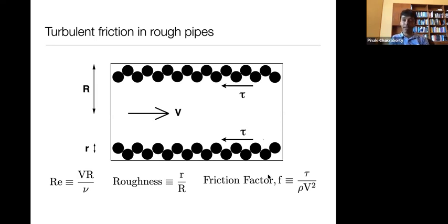The problem that we are interested in is how does the small f friction depend on the Reynolds number and the roughness? The classical experiments, and till date the most comprehensive experiments that show this dependence, how the friction depends on Reynolds number and on roughness, go back to the experiments done by Nikuradse in Ludwig Prandtl's lab in 1933. So I'll show this famous data from Nikuradse.